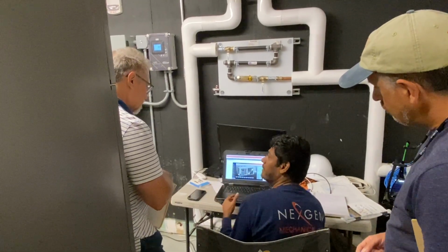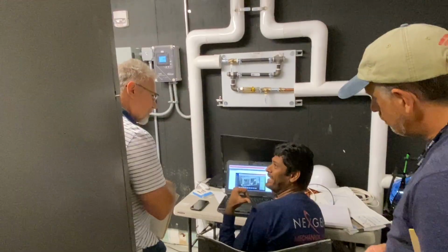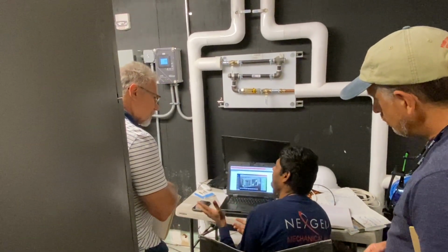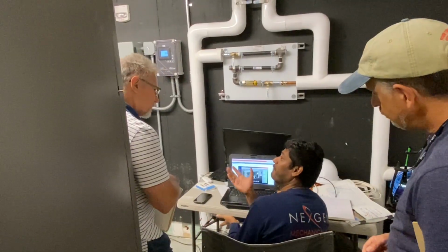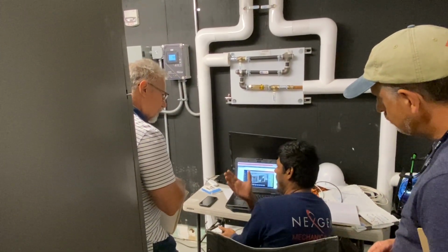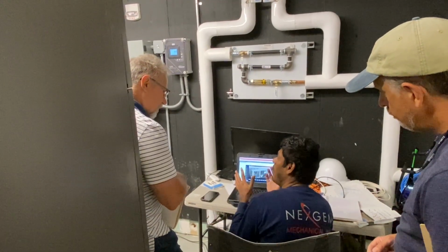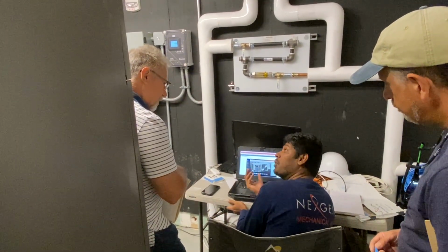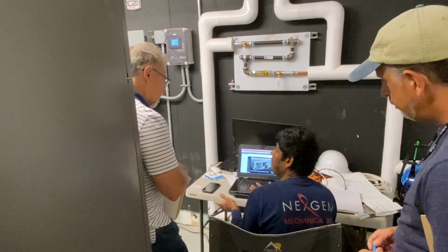But with VAVs, it's not whatever I get, I can cool it. The VAV can only open the damper for cooling. If I open 100% outside air and couldn't maintain temperature, it all depends on what is incoming. I don't have any local control for cooling. So probably that could be the reason.